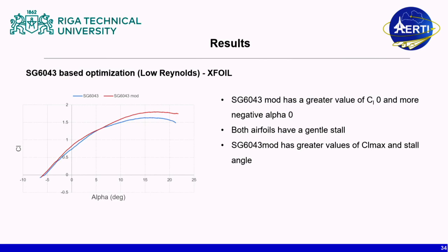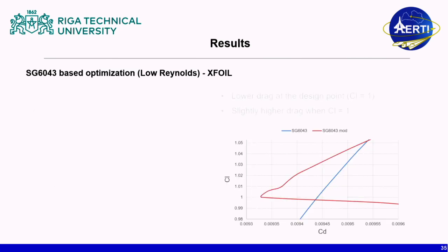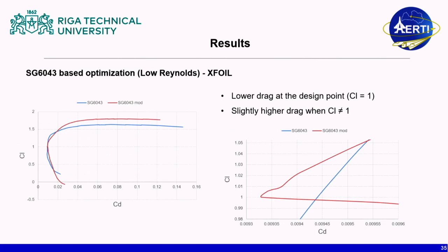First, as you can observe, the newly optimized aerofoil produces more lift than the original base aerofoil. As you can see in the red curve, it produces higher lift than the original aerofoil. Similarly, if you go to the drag, the drag is reduced in the new aerofoil.